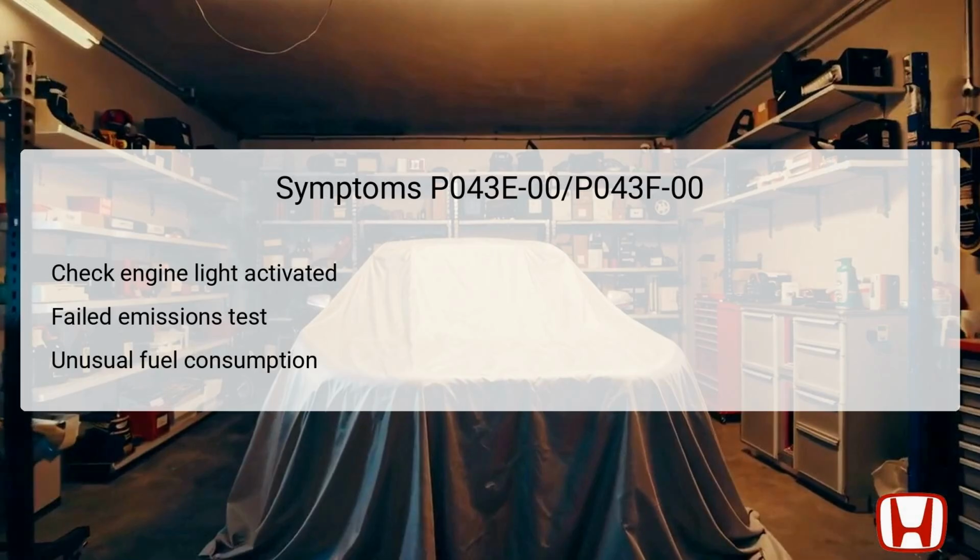Additionally, a vehicle experiencing these codes may fail an emissions test, as these codes are directly related to the EVAP system's ability to manage fuel vapors correctly. Another potential symptom noted is unusually high fuel consumption, as an inefficient EVAP system may lead to the vehicle utilizing more fuel than required. Understanding these symptoms can be vital for timely diagnosis and repair to restore the vehicle to